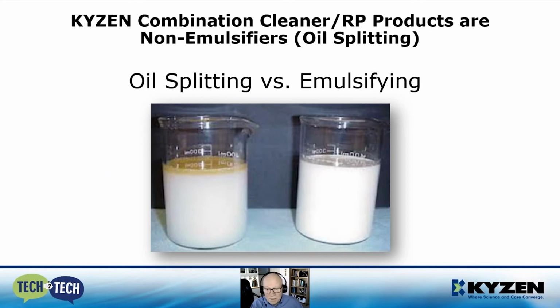I put this slide in here because this is important. The oil splitting products are much more efficient. They clean parts better and longer. The bath life on a splitter is normally 4 to 6 times what it is with the product that emulsifies the oil, which is shown here in the slides.